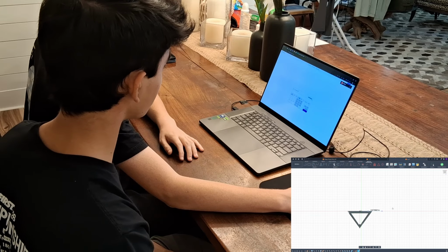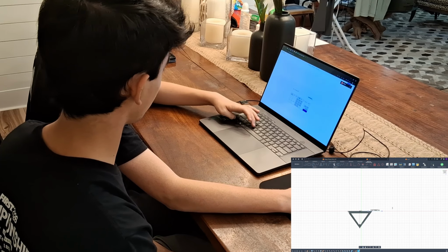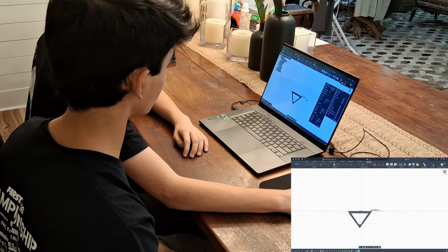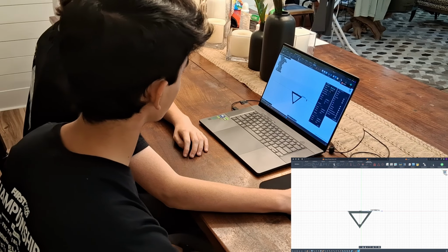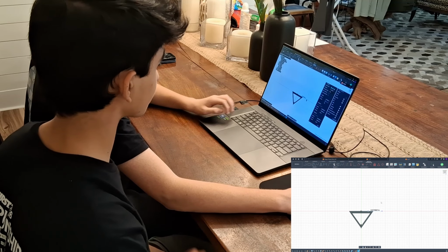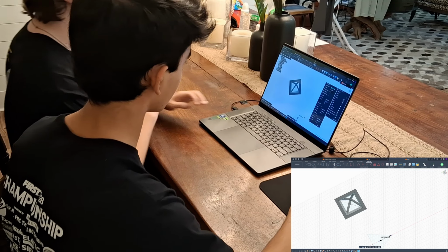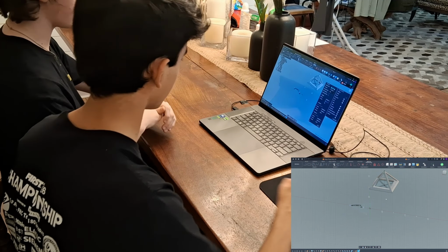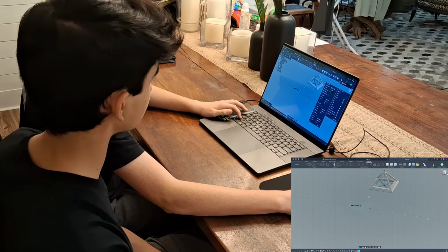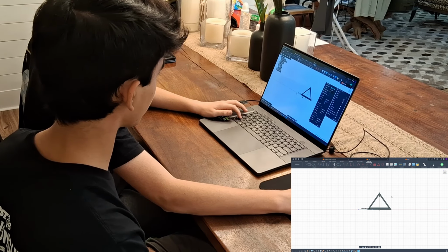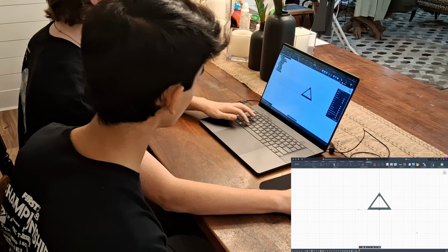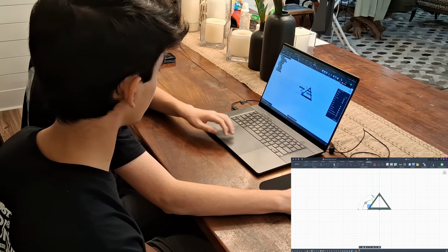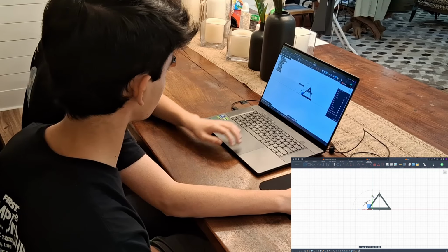So now you copy that number, and that's going to be your height. So make sure we flip it around now. Okay, make sure you bring your line vertically up from that center point. So use your line tool. Go from the center point, and bring it up that much. Now just press enter.